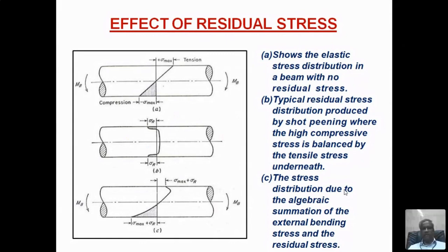Compressive stresses are beneficial because it is pushing, it is crushing the material. When you crush it, when you push it, the crack, whatever crack has grown, will be closed partially. So it will decelerate. It won't stop. Okay, it won't eliminate the crack growth completely, but it will delay the crack, delay the failure. That means what? Delay the failure means what? The fatigue life will be enhanced. Fatigue life will be improved by introducing the compressive stress. Compressive stresses will delay the crack, will decelerate the crack growth, and by that it improves the fatigue life of the component.